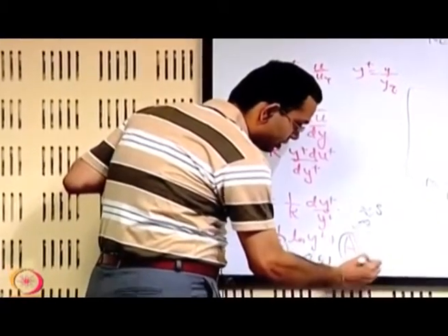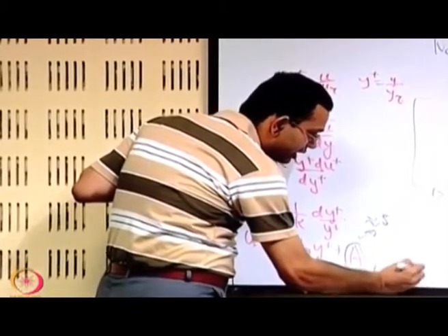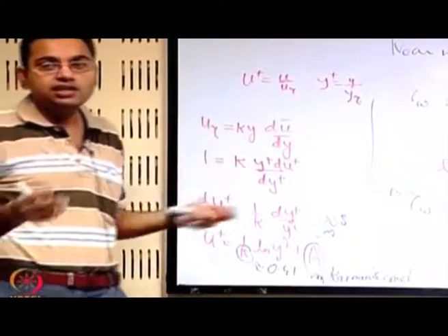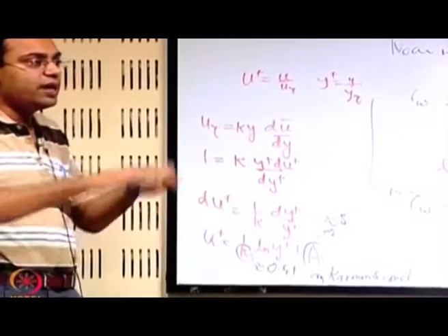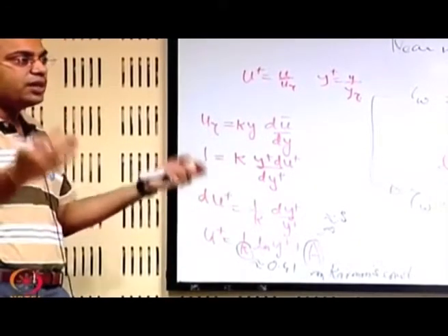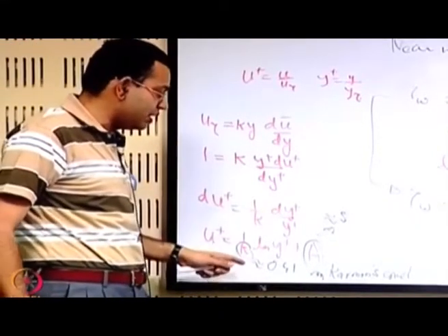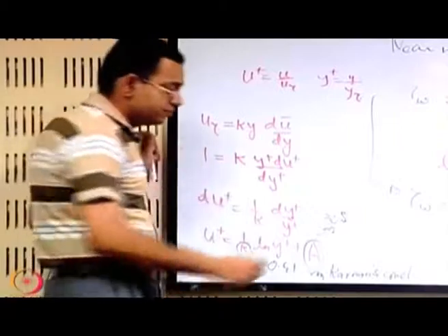So it is not like a theoretically derived constant, but perhaps nature has created things in that way that no matter whatever is the roughness, no matter how the turbulent structures are distributed, wherever this law is important, this is known as a logarithmic law, log law.